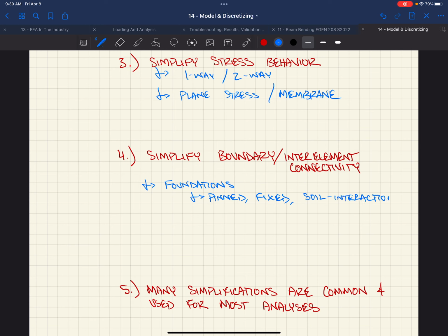And the code allows us to do that. We start putting springs under our foundations. The spring constant we use is based off of a geotech investigation. Another fellow civil engineer goes out there, kicks the dirt a few times, feels how...